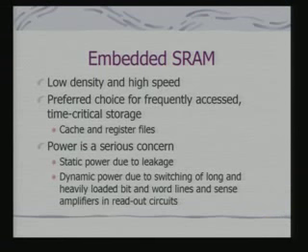A typical feature of an embedded SRAM would be obviously low density, because I am using 6 transistors per bit, and high speed. And this is a preferred choice for frequently accessed and time critical storage like cache memory and register files. And in fact, you have seen in processors like PIC, your entire memory is organized as a register file, and there this would be basically static RAM.